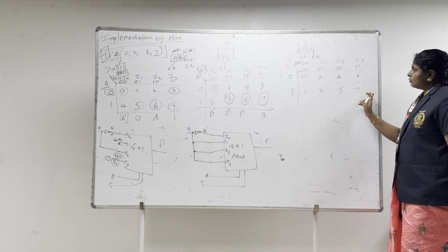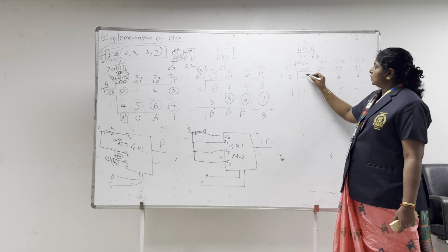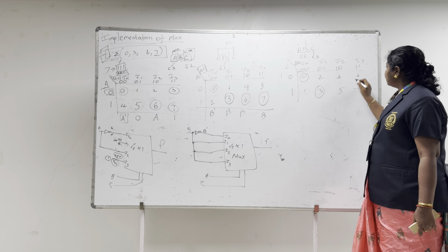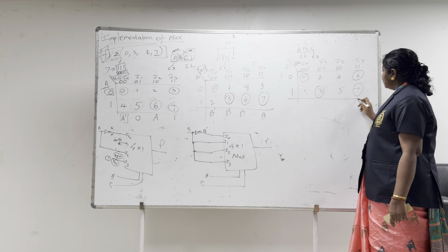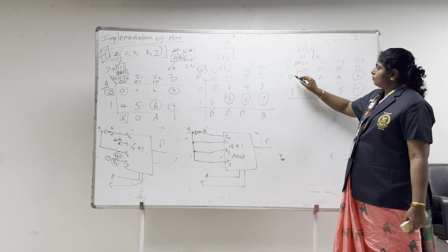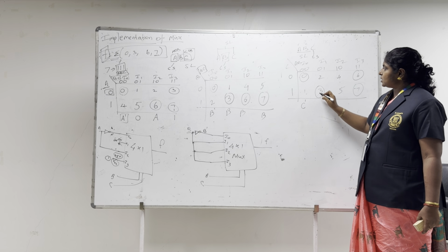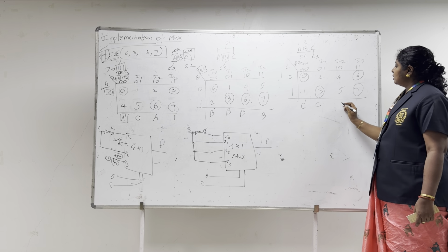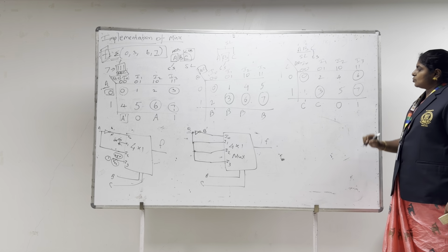And if this is the configuration, C is my control signal, AB as my select lines. For the same question, the implementation is F equal to minterms 0, 3, 6, and 7, right? So over here only this has been selected, and therefore C bar. Here this has been selected, therefore C. Both are not there in that logic, therefore it is 0. Here both are there in the logic, therefore it is 1.